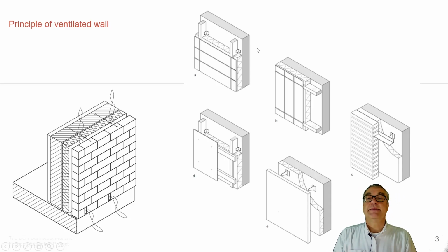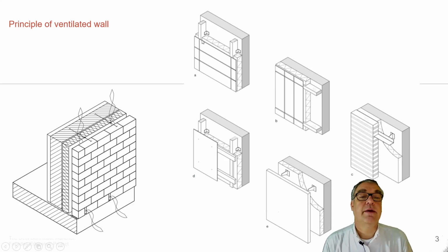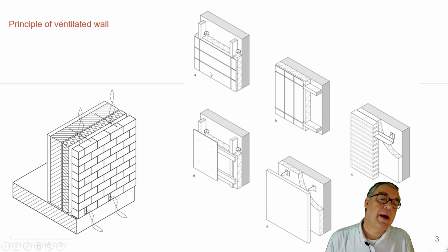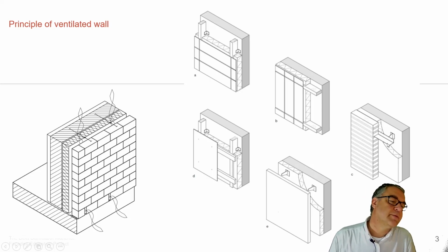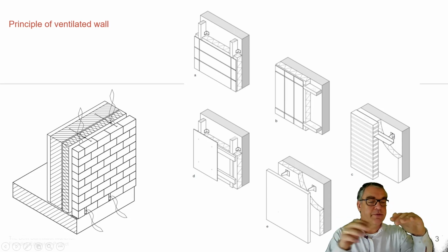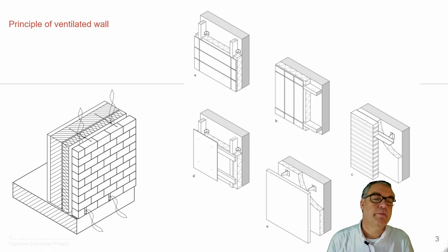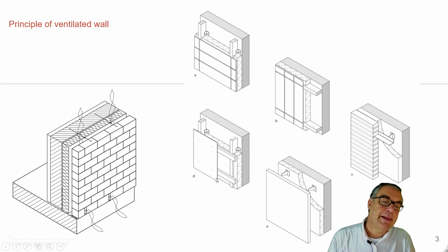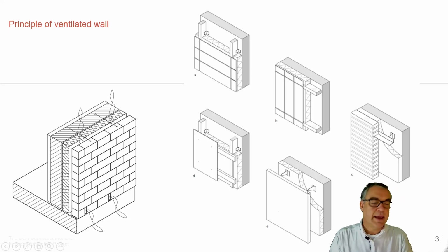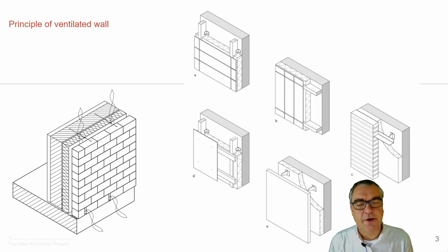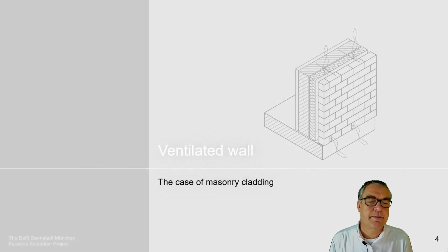We can divide these ventilated cladding systems into horizontal or vertical cladding systems with a substructure. This is a masonry system, which obviously also needs a substructure, some brackets to take the dead loads of the masonry into the main structure. There is also a metal cladding on a subsystem, or a metal cladding on a bracket system, which individually keeps the positions of the outer cladding layers.